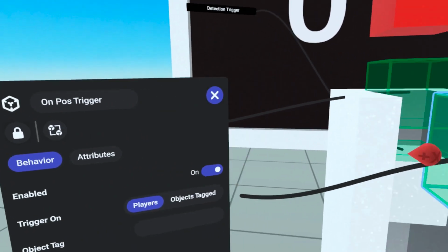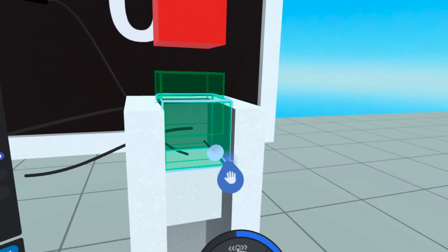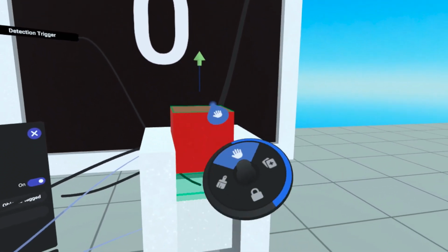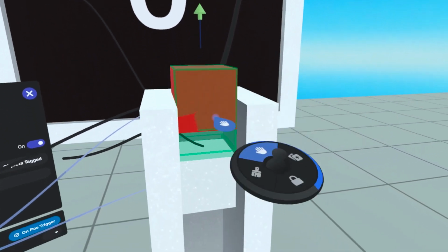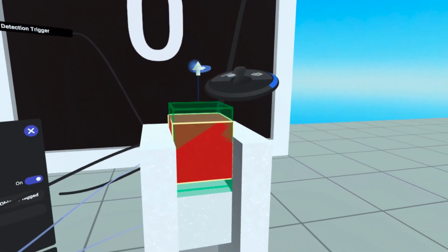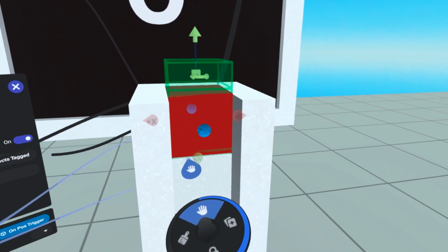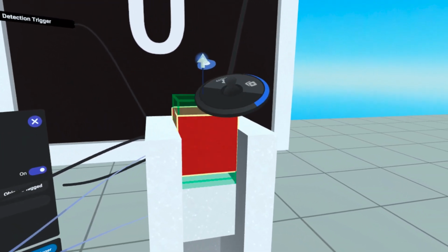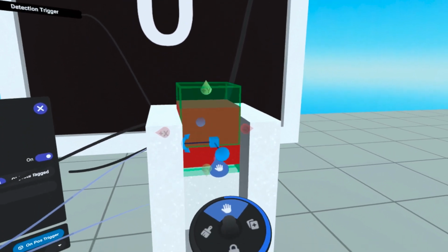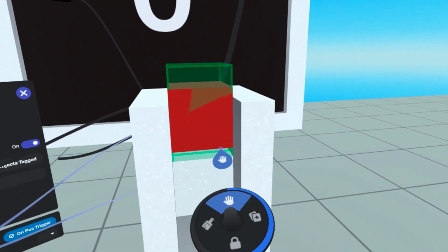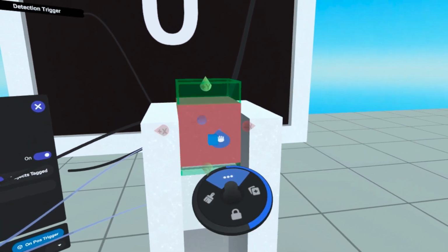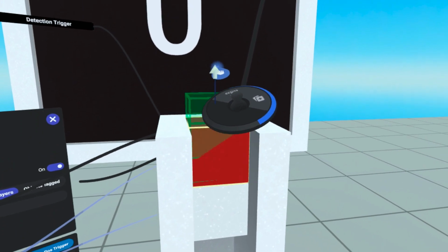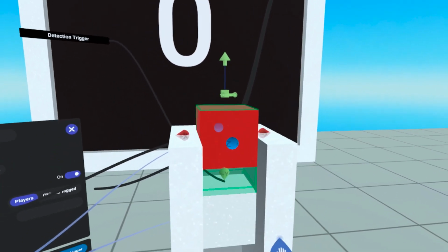Let's put another trigger at the location we want the button to be when it's in its depressed state. The button will start with the top trigger as the target position for its spring. Then, when the button is pushed and has entered the detection trigger at the bottom of the travel space, we'll change the spring target to be the trigger we placed at the depressed position. This position should keep the button slightly above the detection trigger, so once the button is no longer being pushed, it springs back up out of the trigger and is ready to be pushed again to enter the detection trigger.